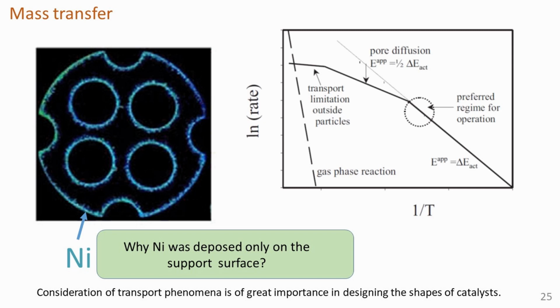In order to fulfill the above mentioned requirements for the catalyst, the particles are usually made of ceramic material of cylindrical shape with one or more internal holes, as seen in the figure below. The use of such catalyst formulations is often developed together with a new reactor concept, aiming at a higher effectiveness factor than achievable in conventional steam reforming.